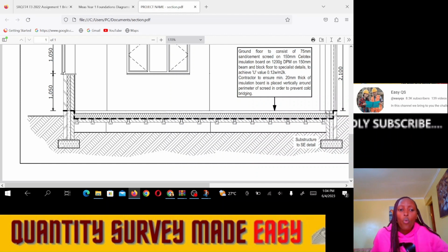So this will be the trench. All right. Below here, we have the concrete, the mass concrete in the strip footing. Then here we have the wall, the masonry wall going up. Maybe we could have the brick, the cavity, and the block work. All right. So what I want to explain is the foundation spread. The foundation spread is this space between the edge of the foundation and the wall. The edge of the trench and the wall.